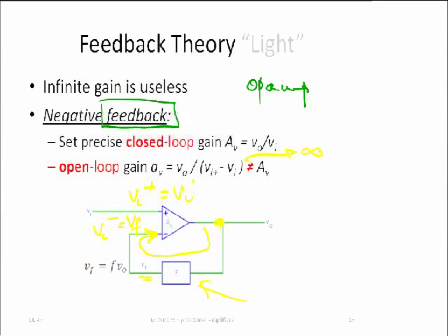Okay, any more questions about that? Yes. So for an ideal amplifier, Vi plus equals Vi minus. Okay, yes. So that gets to this question. Well, if this is infinite, what do these voltages have to be, and so on? You're right. What you said just is correct. I just want to say it again with a different slide that is just for that purpose. Okay, we're actually even going to calculate it. But you have seen that in the book, and you may also from intuition say, hey, these voltages have to be equal. Your intuition is correct.